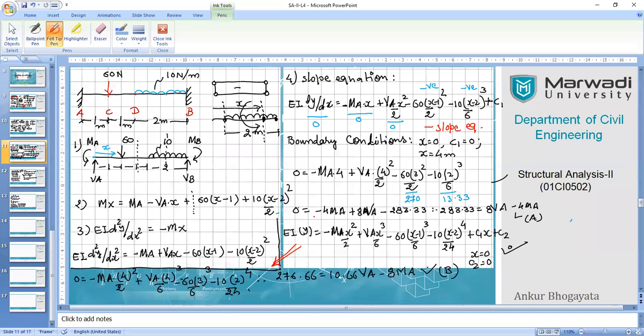Here, this was the major point, right? Because in the earlier numerical we only ended up our calculation by using the slope equation only. Why? Because loading was symmetrical, both values of MA and MB fixed moments were equal. However, in this case, the moment at A and moment at B are definitely not going to be the same. So we cannot assume this.